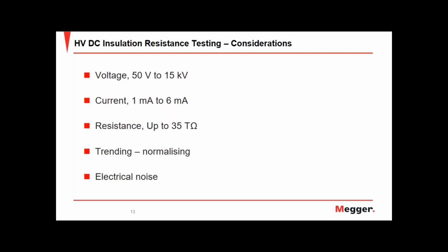We have a basic filter, which is, as I said, always switched on. And then in addition, we can add a hardware filter, which is a low pass filter designed to take out various frequencies, including 50, 60 hertz mains frequencies and their harmonics, and of course, frequencies much greater than that as well. There's also long duration fluctuations, where, for example, you may have some environmental thing that's changing.